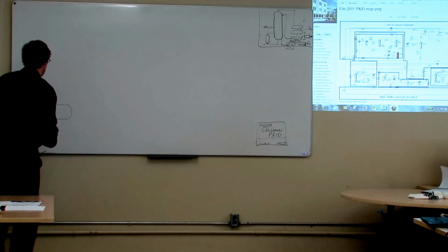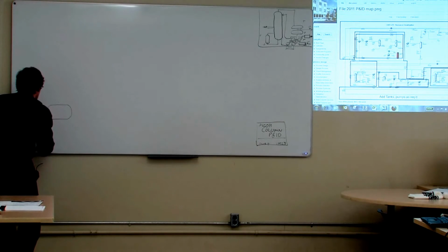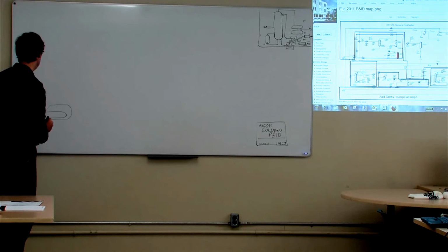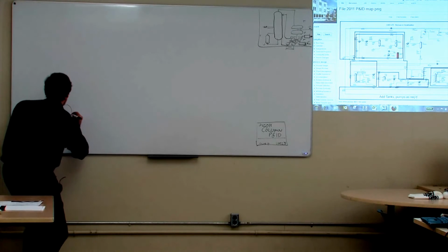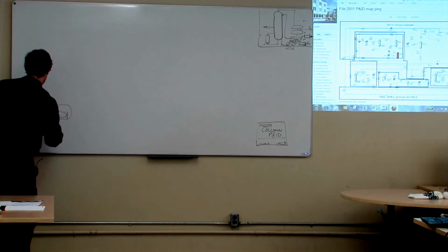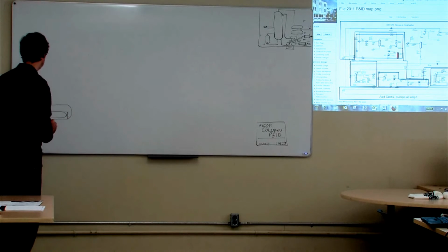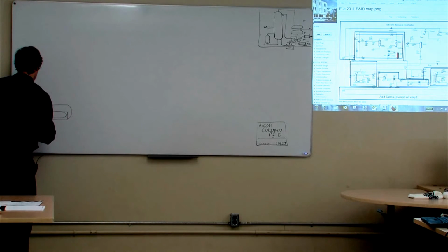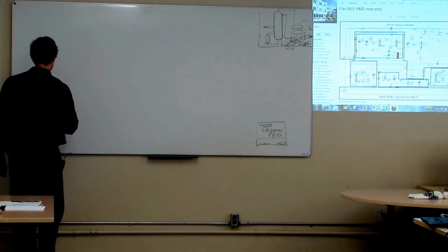There's the outline there. I'm going to draw the tube sheet here. There's the tubes in the kettle reboiler. I'm going to put a baffle so I have an overflow on the kettle reboiler. So the liquid level is going to sit kind of there. I'm going to show my steam coming in here with a nozzle and my steam coming out. I need a vapor.